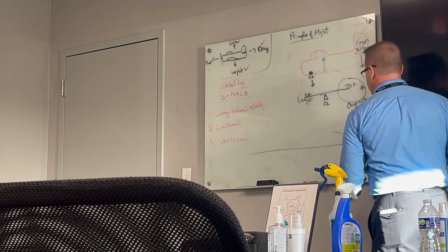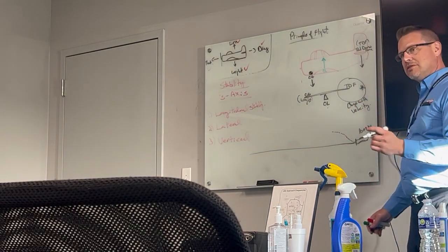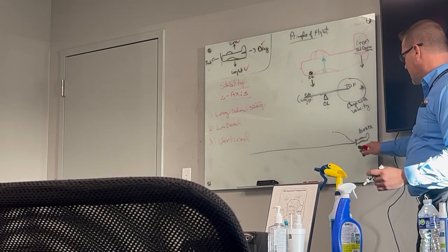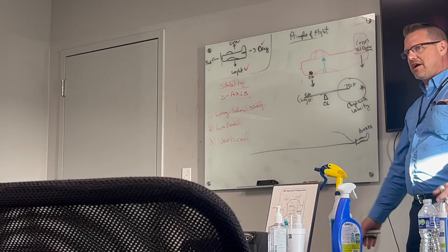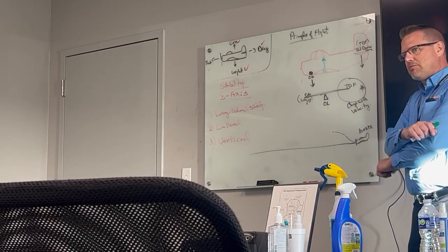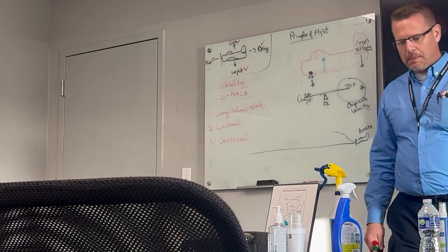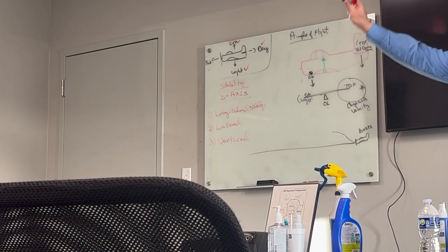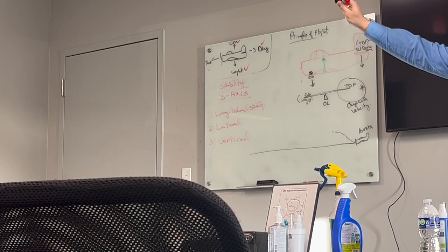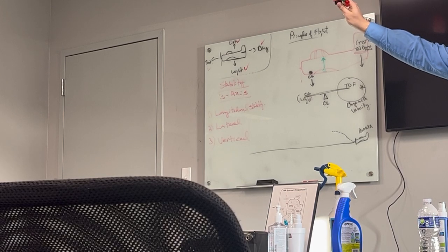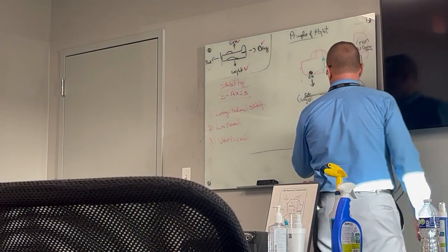Is it a positive dynamic? It does have positive dynamic, but my question is, if we did nothing, you're sitting inside the plane with your arms crossed, there's no intervention from the pilot, the plane starts going up, and you don't change the power setting, what is the plane going to do? Airspeed is going to decrease, right? So our airspeed is going to go down to probably about 90 knots.